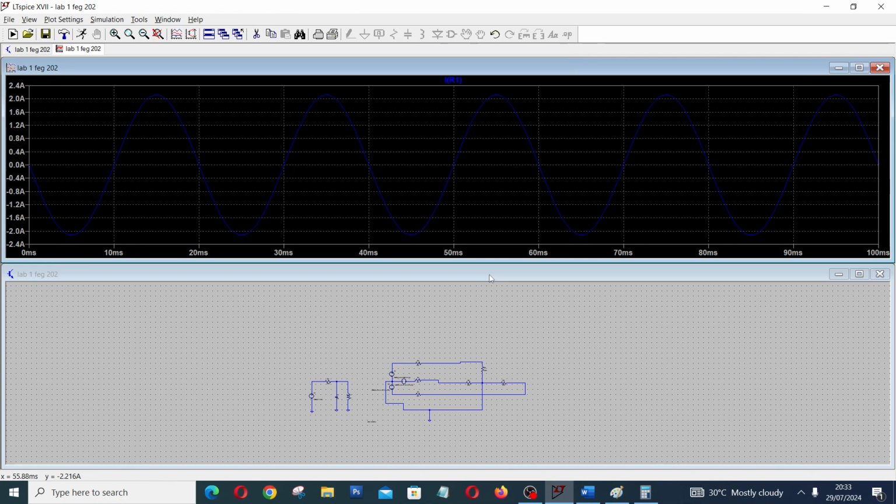Lagging power factor. Power factor is just a matter of the ratio of the power generated by the generator that gets to the load. But when the system is too inductive, a larger portion of the power generated by the generator will not get to the load, but will be wasted in the field of the inductor, and that will create what we call lagging power factor. To correct that, we use a capacitor to compensate, because a capacitor in itself supplies apparent power when the voltage gets to zero.